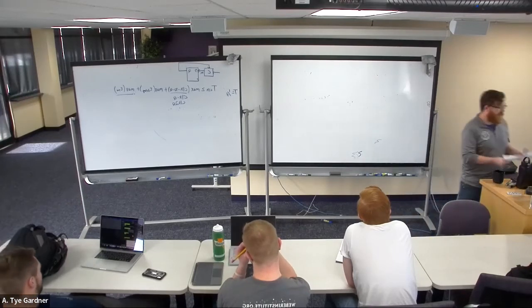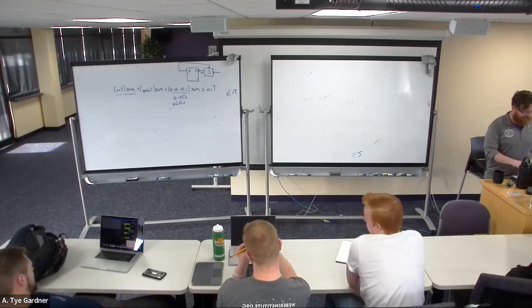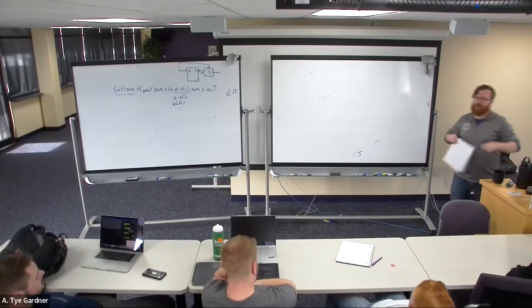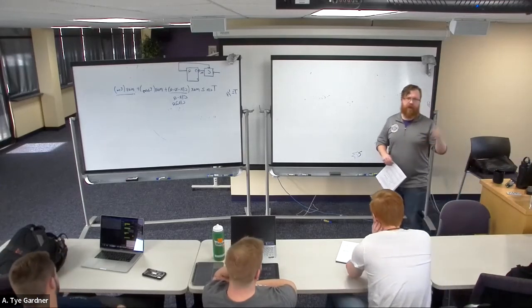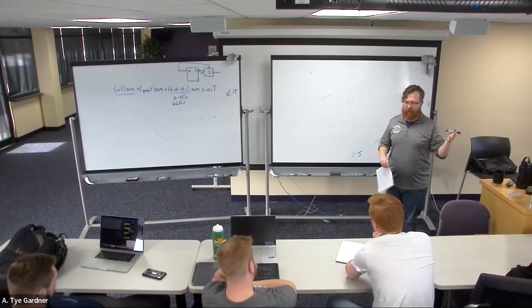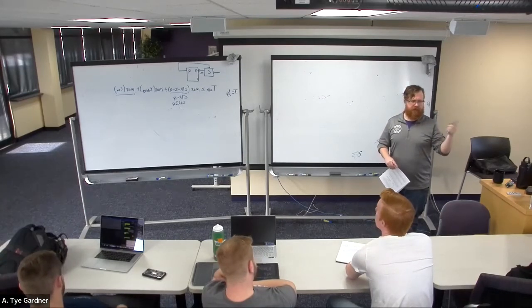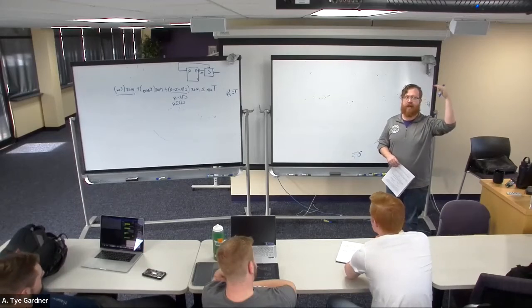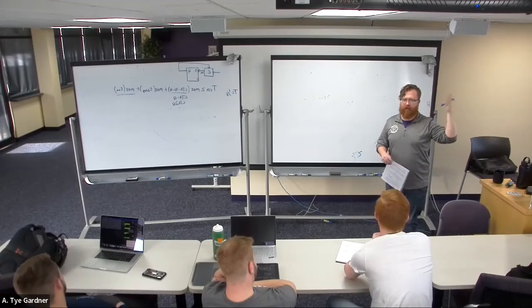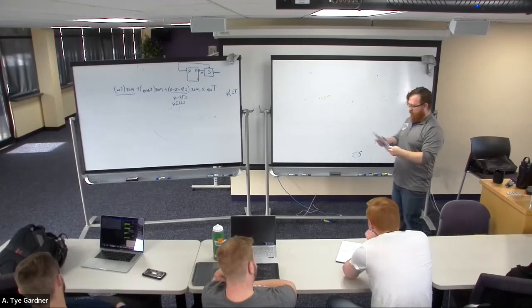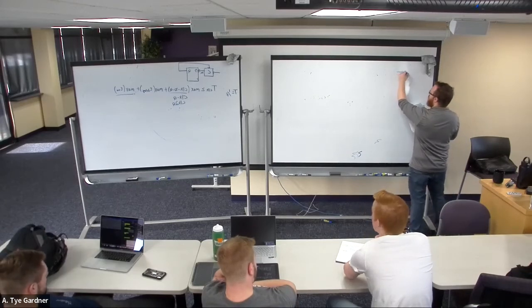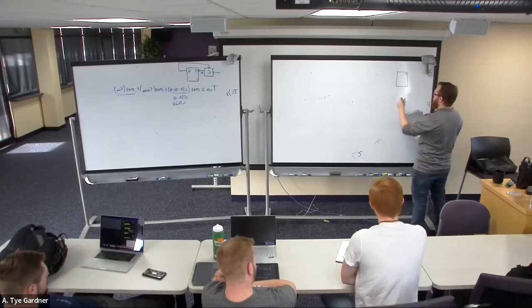So let's talk then about applications of these flip-flops. And if you recall last time when I talked about JK, I pointed out that if you connect the J and K inputs together to the same input signal, it becomes just what was called a T flip-flop, right? Because it's either staying the same if it's 0 or toggling if it's 1, meaning it changes. So it's called a T flip-flop for toggle. Well, we're going to use this to build one of the most commonly used devices in digital logic, which is a counter.